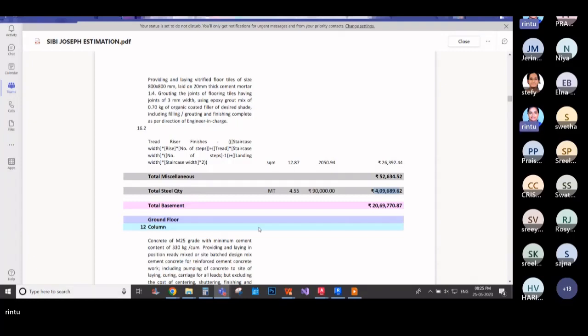Now on this machine, you can see the operation. Once the power is on and the rebar is placed, you just have to push the bar in position, and it will bend automatically. This is a 42 mm thick bar they are representing in the video. You can bend it in different methods. You can even bend more bars at a time when the number of bars to be bent is more. So it saves time, saves energy, and only one person is required to operate and place the bars in position. It will be easy, fast, and you'll get all the work done.